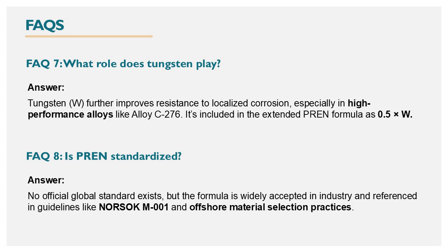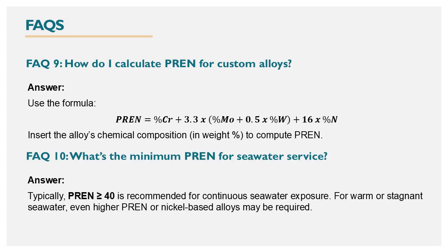Question number 8. Is PREN standardized? The answer is, no official global standard exists, but the formula is widely accepted in industry and referenced in guidelines like NORSOK M001 and offshore material selection practices.